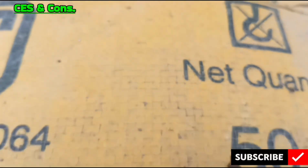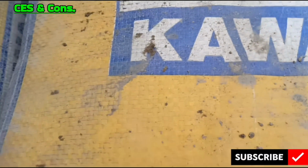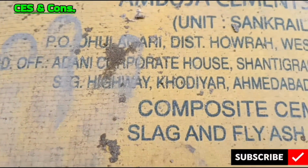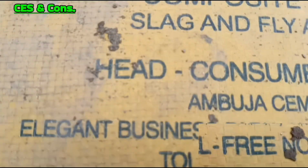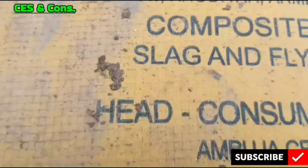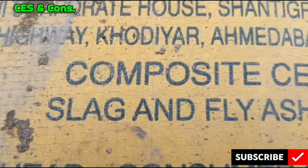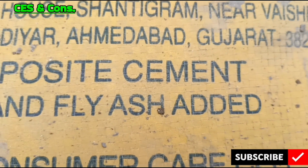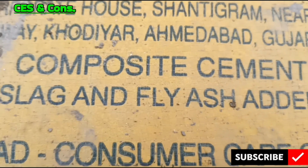Number 1. Fineness. This is as per IS 4031 Part 2. The minimum specific surface should be 225 meter square per kg. Number 2. Setting time. This is as per IS 4031 Part 5. Initial setting time not less than 30 minutes and final setting time not more than 600 minutes.